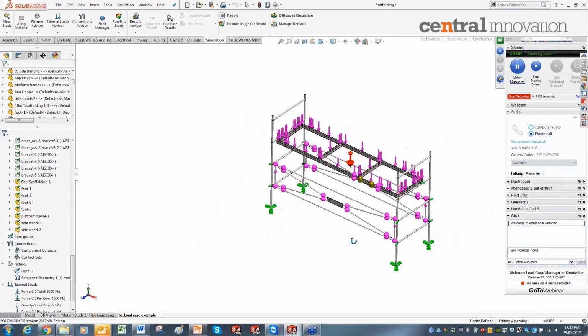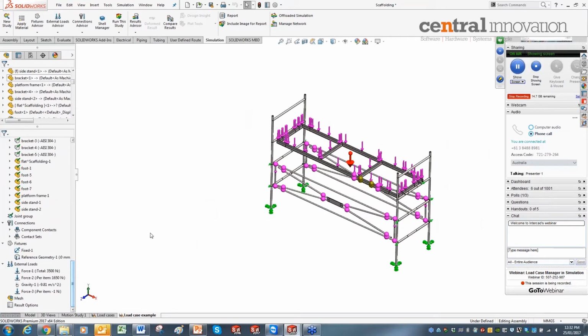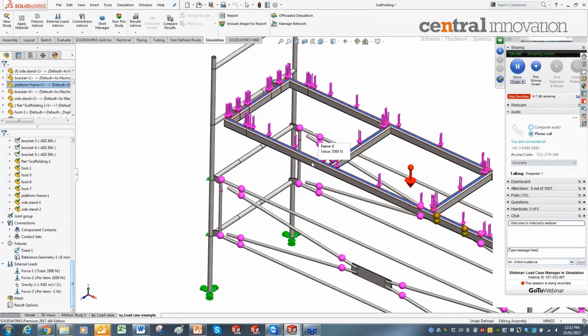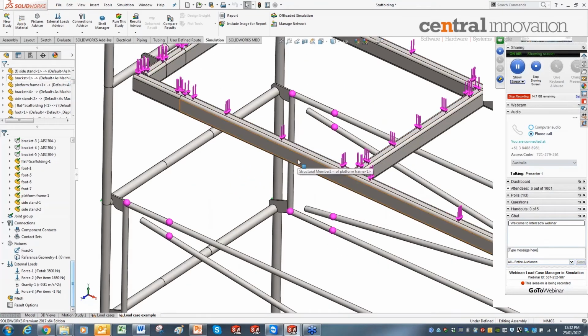Okay, now I have specified all loading definitions and all fixture definitions I need for the setup, and I can copy the mesh from the predefined study. I need to refine the mesh. I need to apply mesh control on these rectangular tubes because those are treated as solid elements, not shell elements. I mean these rectangular tubes in here, the top platform, those are solid elements.